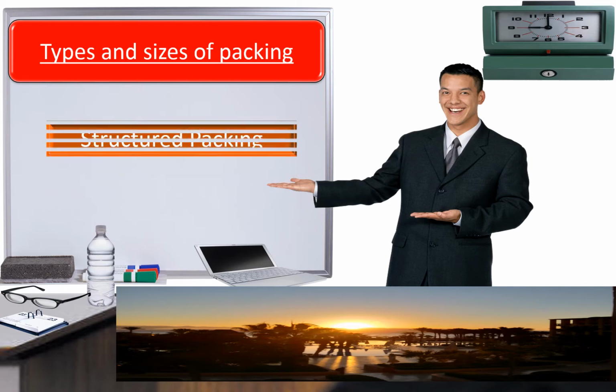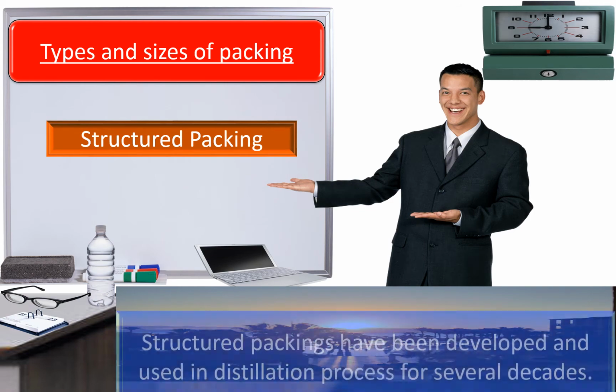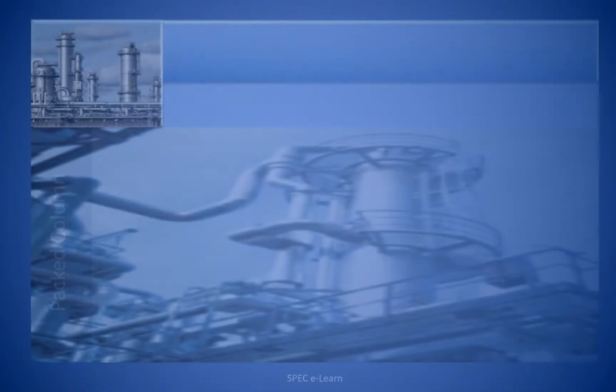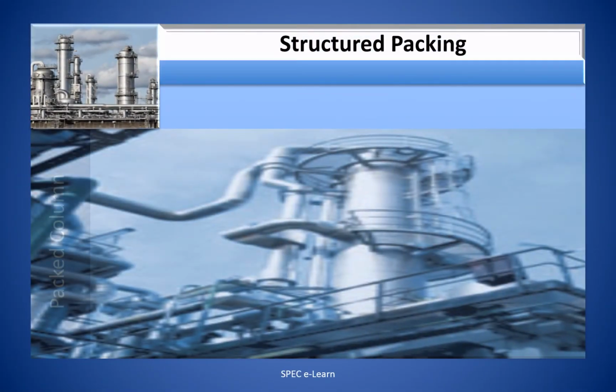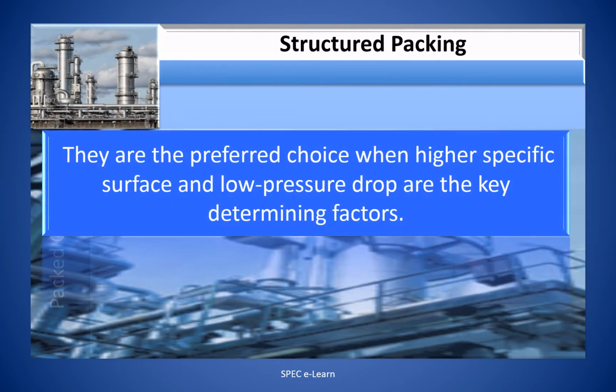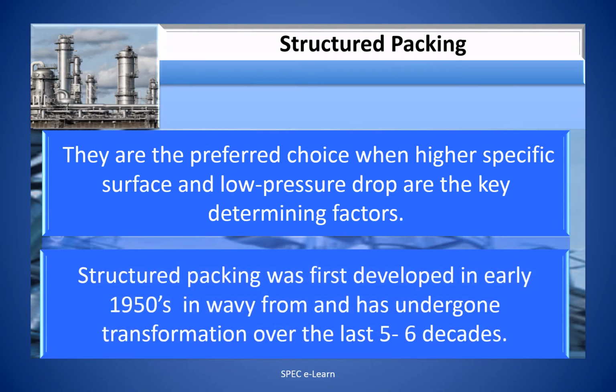Structured packing. Structured packings have been developed and used in distillation processes for several decades. They are the preferred choice when high specific surface and low pressure drop are the key determining factors. Structured packing was first developed in the early 1950s in wavy form and has undergone transformation over the last 5 to 6 decades.